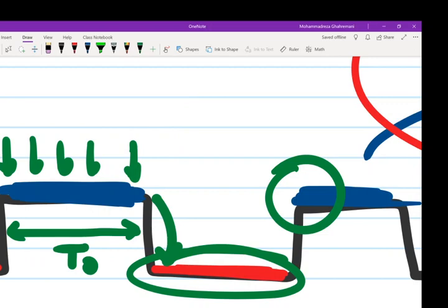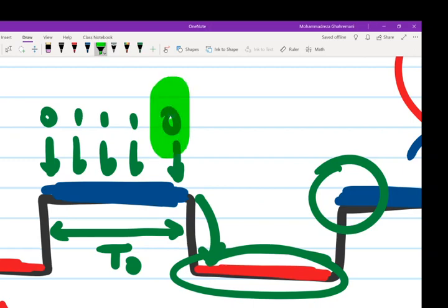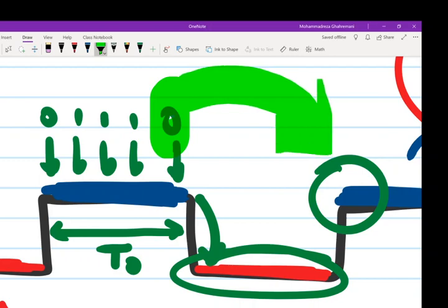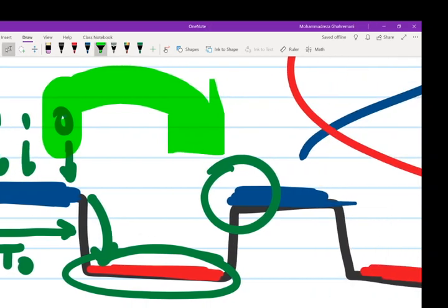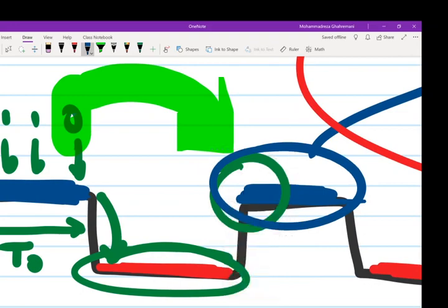So if we assume the value of the input, for example, it's 0, 1, 1, 1, 0, the last bit of the information of these 5 bits is 0. So this 0 will stay like a constant on the output until the next activation period. At the next activation period, we look at the inputs. If the input has any change, that change will be reflected in the output.